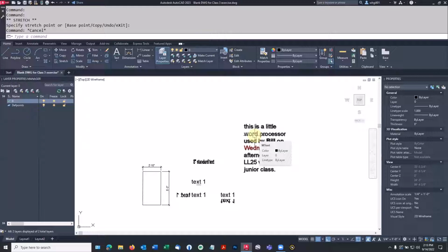This is the most important thing all day, which is, how big do we really want our text to be in the drawings? The big stuff, you can make whatever you want, but text for notes needs to be big enough to read, and not only read, but read when somebody produces a half-size set, scales it down to fit in drawers. So this needs to be twice as big as the minimum height that can be read. The Army Corps of Engineers says they want everything to be 1/8 of an inch high, so it can reduce to 1/16, which we can still read.